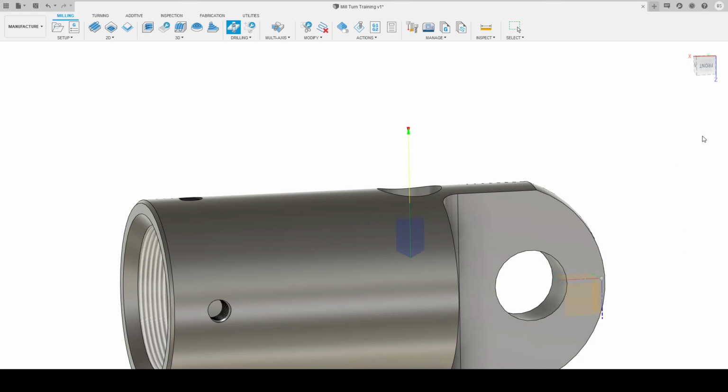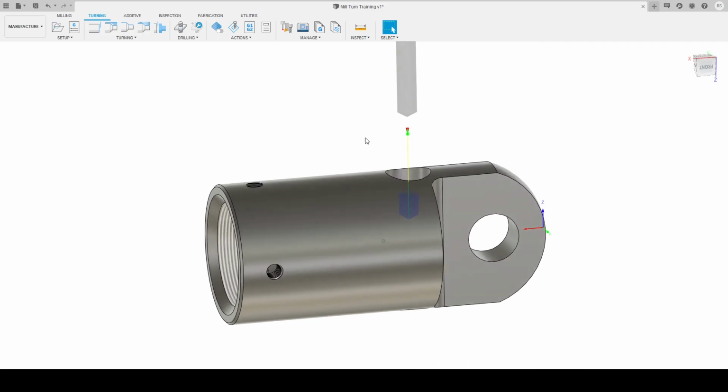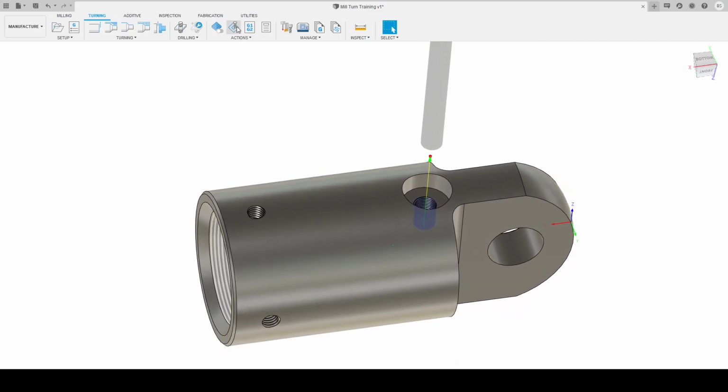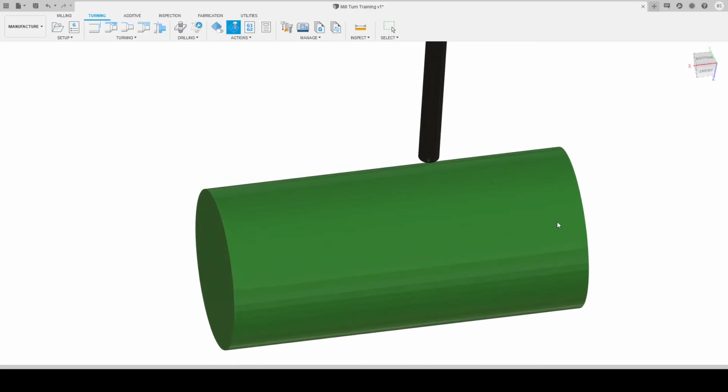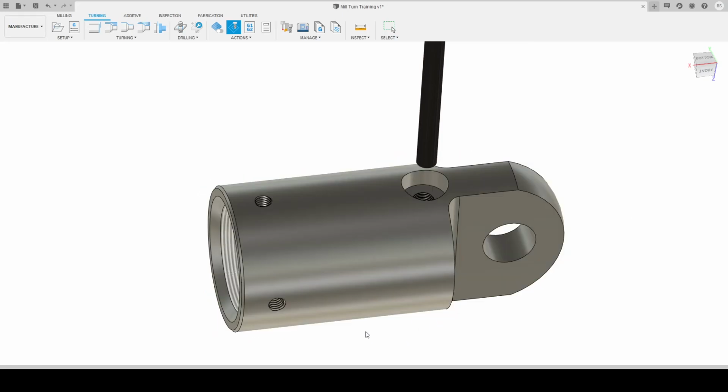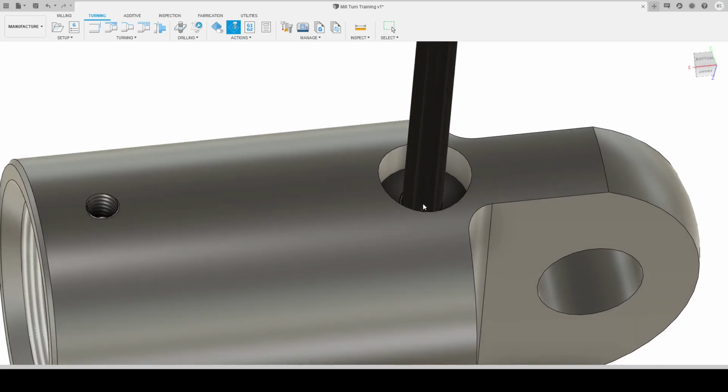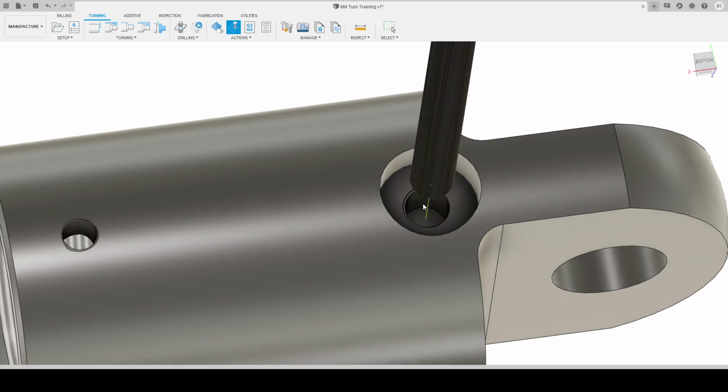So let's do that. We'll do 1mm peck, so it'll go in 1mm, retract fully, do another 1mm, retract fully. In real life, you wouldn't do a 1 mil, you'd say 3, but for such a shallow hole, we probably wouldn't even peck anyway. Alright, so let's simulate that. Let's turn our stock off and let's simulate our drilling. Very good.